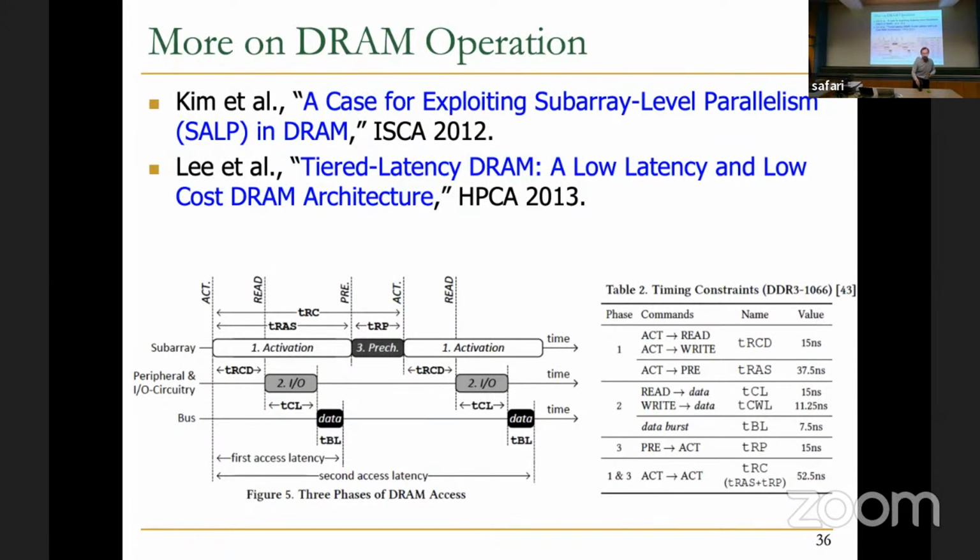Exactly. Basically, what you're getting at is that the timing constraint needs to correspond to the longest possible time that the DRAM needs to respond. So that's the problem with the single timing constraint. That's why this has evolved this way. All of these different operations have different timing constraints.